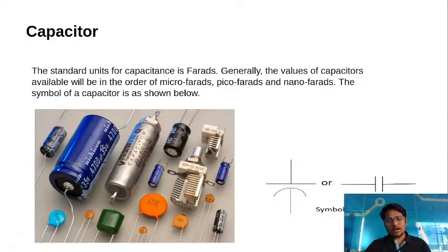You cannot give voltage more than the rated voltage. So the voltage rating is 35 volt. This is the breakdown voltage of the capacitor. If you give more than this voltage, it can be dangerous and all your components can be damaged. So these things we have to keep in mind. Always keep in mind, you never give the voltage above the rated voltage.